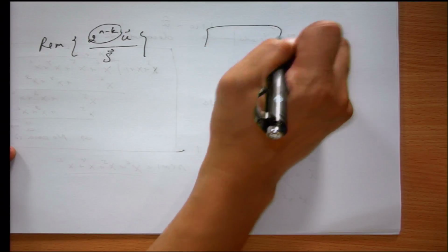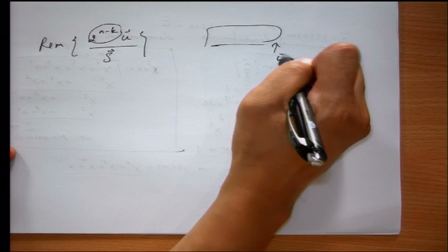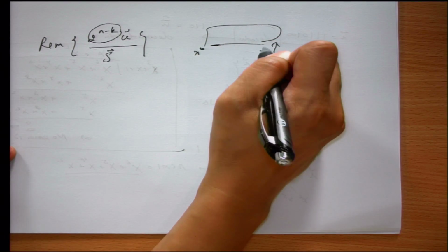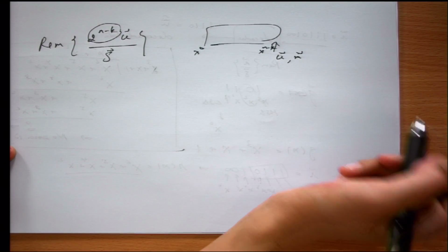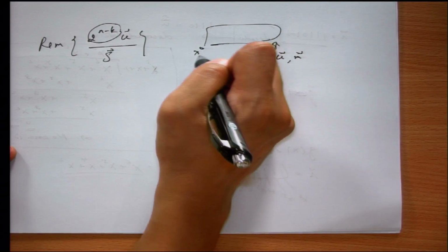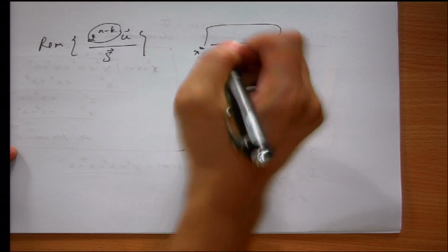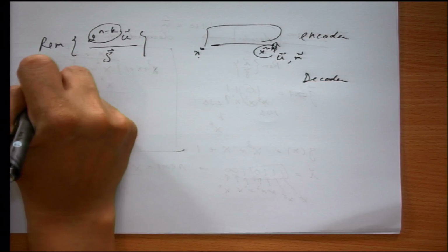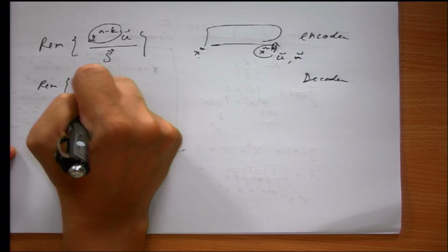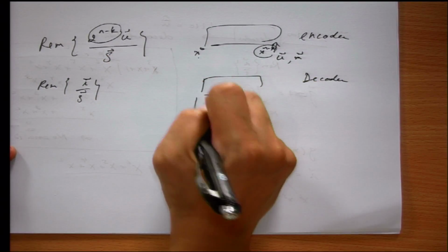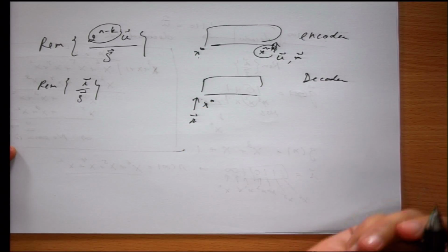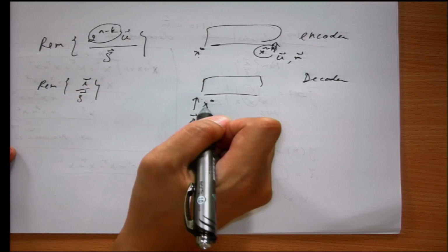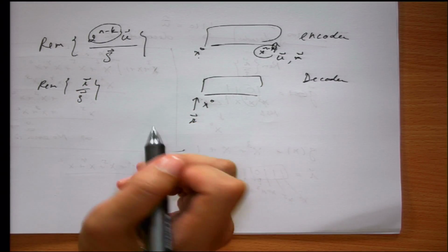So this is a circuit. You put the data, U or M, on the right hand side because this is the x to the n minus k position. The left hand side is the x0 position. This is the encoder. But at the decoder, you find the remainder of R over G. So you have to put R over here because this is the x to the 0 position. You didn't multiply R with anything, so you have to put it on the left hand side of the circuit.